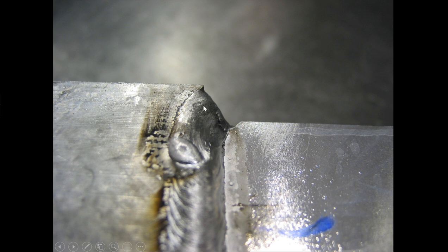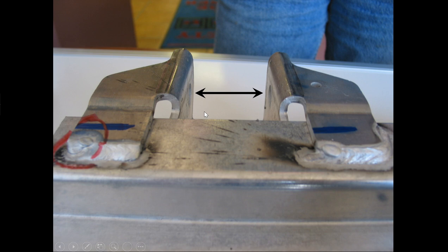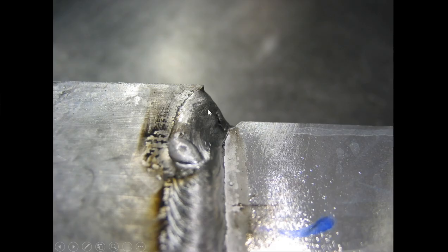This is basically end notching because we got the arc so close to this edge. If this doesn't have to be a continuous weld, I would start a weld going this way, and I'd start a weld going the other way. Things we would do from design. But until we get these things nailed down, and as much as you think we can perform miracles, we've done something wrong.